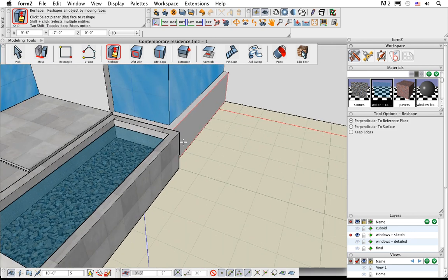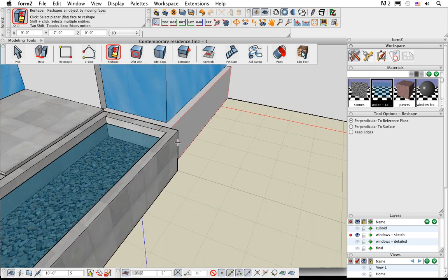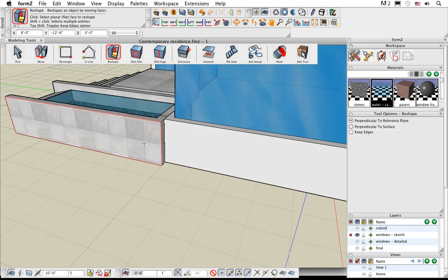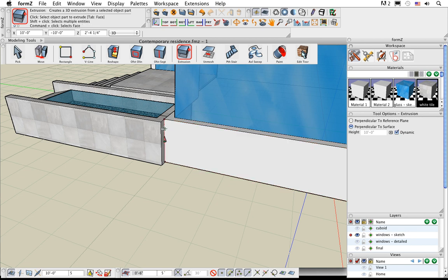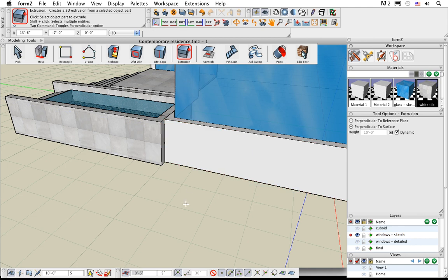The reason I did that is so that the tiling can continue on along the front face of the existing stucco wall that's here. Let's go ahead and do that. Let's spin this around to this view over here and use the 3D derivative extrusion tool. I'm going to click on the face here and pull it out. The whole face boundary of the back of the water garden is a little bit bigger than what I want. So let's escape and cancel out.